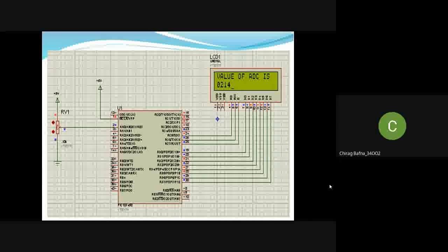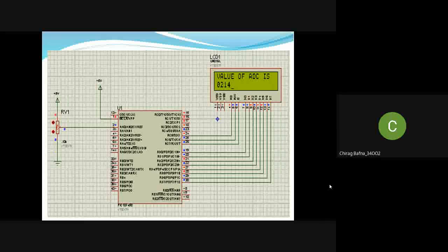The fact that we have multiple analog input channels and a single digital output register makes it necessary to have start conversion, that is SC, and end of conversion, that is EOC, signals. When SC is activated, the ADC starts converting the analog input value of Vin into an n-bit digital number. The amount of time it takes to convert varies depending on the conversion method, as was explained earlier. When the data conversion is complete, the end of conversion signal notifies the CPU that the converted data is ready to be picked up.